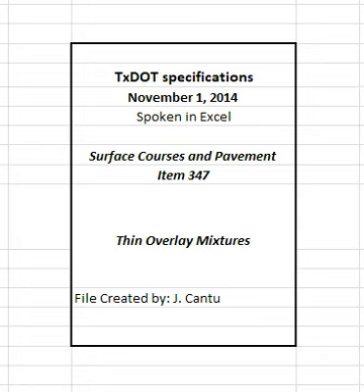Supply intermediate aggregate from coarse aggregate sources, when used, that meet the requirements shown in Table 1 unless otherwise approved. Test the stockpile if 10% or more of the stockpile is retained on the number 4 sieve and verify that it meets the requirements in Table 1 for crushed face count, TEX 460A, and flat and elongated particles, TEX 280F.